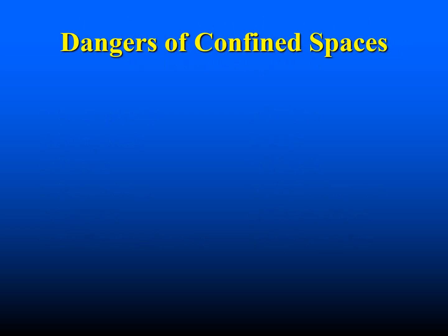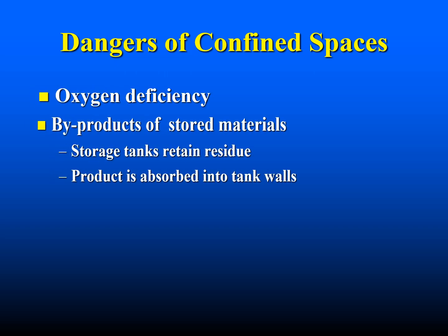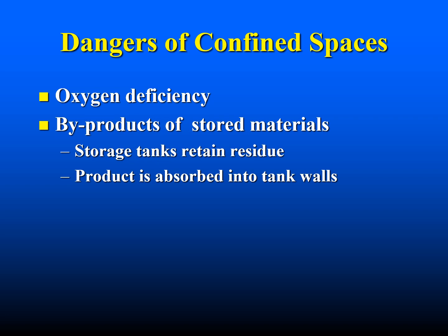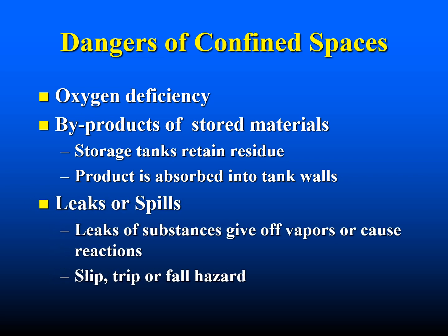Let me go over some dangers of confined spaces. They could be deficient in oxygen. They may contain byproducts of stored materials, such as in storage tanks that could retain the residue, and the product could be absorbed into the tank walls. They could have leaks or spills, so they could leak a substance which would give off vapors or cause reactions, and they could create a slip, trip, or fall hazard.